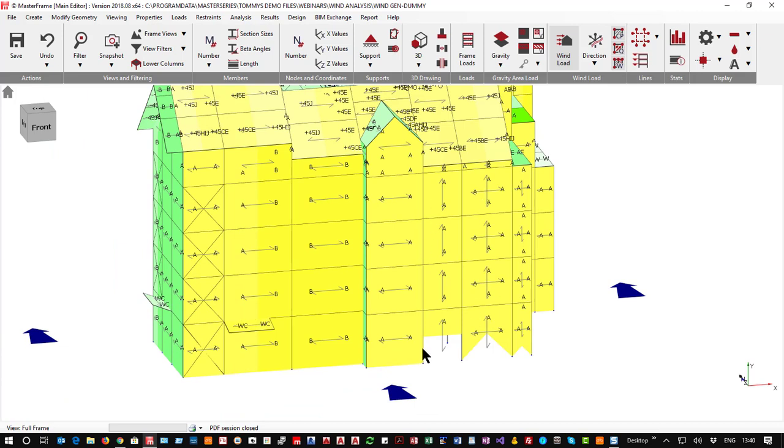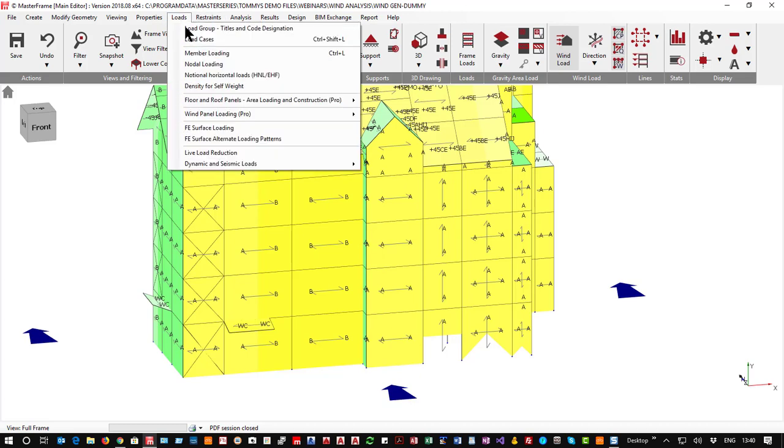Because each of these panels, this column, and then this one, and then this one, are all handled separately, but they are in reality one big panel. Doesn't matter about the spanning direction. So what I am going to have to do is tell it that for classification purposes, glue them back together again. So not a big problem.